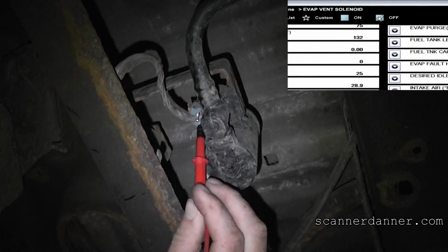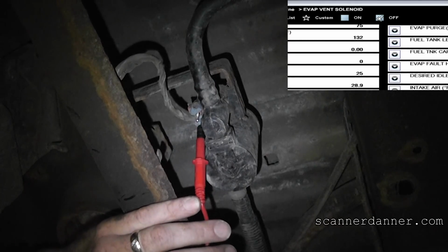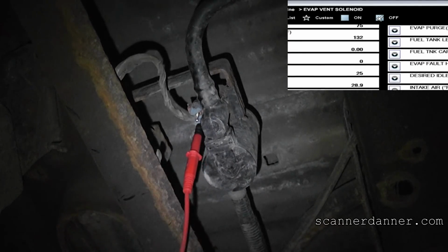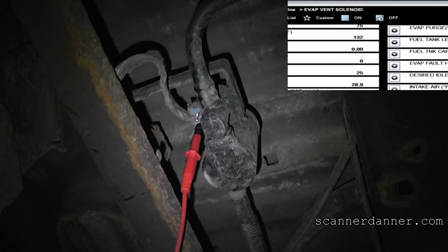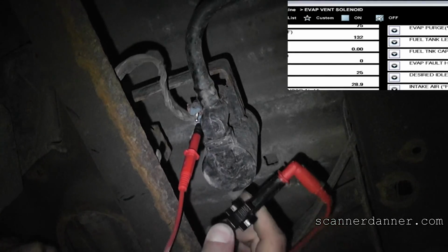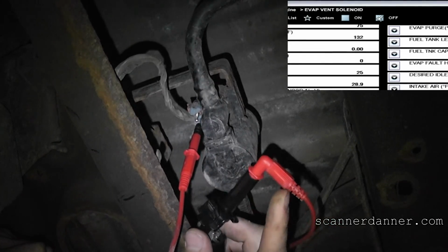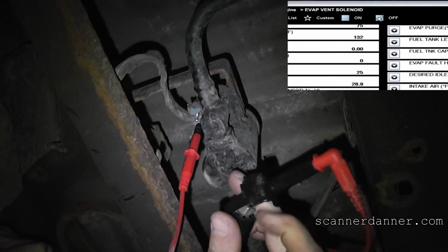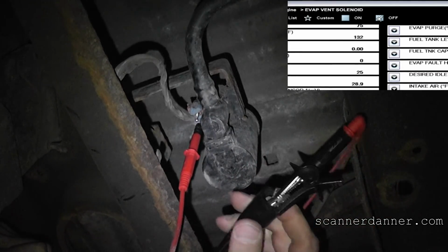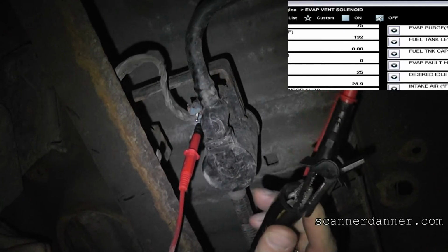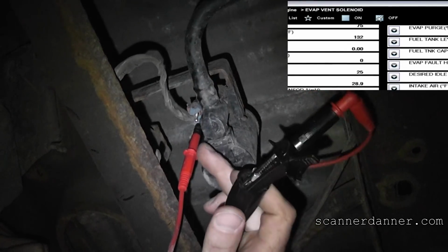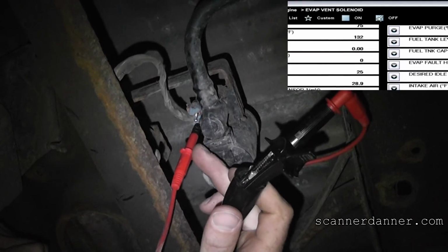And I'm going to use my red positive lead as my power source for my test light. You follow? And I just adapted my test light. I'll let you guys see what I did. Just being creative with what I have. Took the positive lead off my multimeter, put my black alligator clip so I had one, then I connected my test light to it. You see it? So do you see that my test light's essentially connected to my red white wire, which is up here? You guys understand what I did?